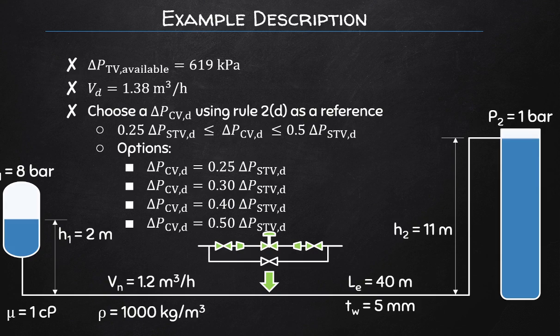What generally happens is, for example, you'd have a pump. In this case we have a high enough endpoint pressure difference to drive the flow, but if you have a fluid mover, in this case the fluid mover would add a bit more extra energy to the system that's not actually required to meet the flow rate, and we would use that extra energy in our control strategy. So here we have the following options given to us, and we need to then choose a conservative choice.